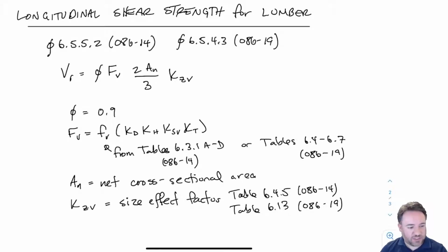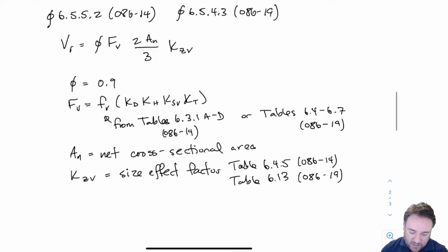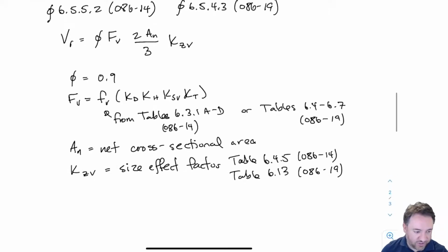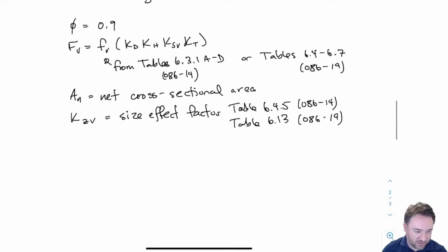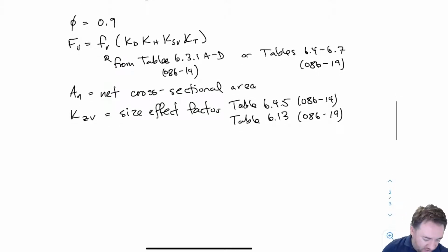And that's why we had to treat it separately, because for compression perpendicular, when we had the stress going all the way through the section, we had a larger deflection resulting. So now that we're talking about shear, we have basically the flip side of that, which is that in those regions near the support, we don't have any significant shear going through the beam, and therefore we don't have to consider the shear in that location. And we're going to clarify with a drawing.